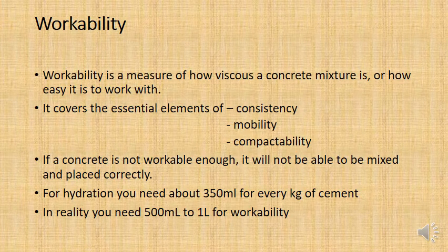I now want to talk to you about workability. Now, this is related to setting. Remember what I said about the concrete going solid, and if it goes solid too quickly, it goes from being very runny to a very thick, viscous sludge very quickly. You're not going to be able to place the concrete. You're not going to be able to mix it and transport it. You're not going to have the time to do that.